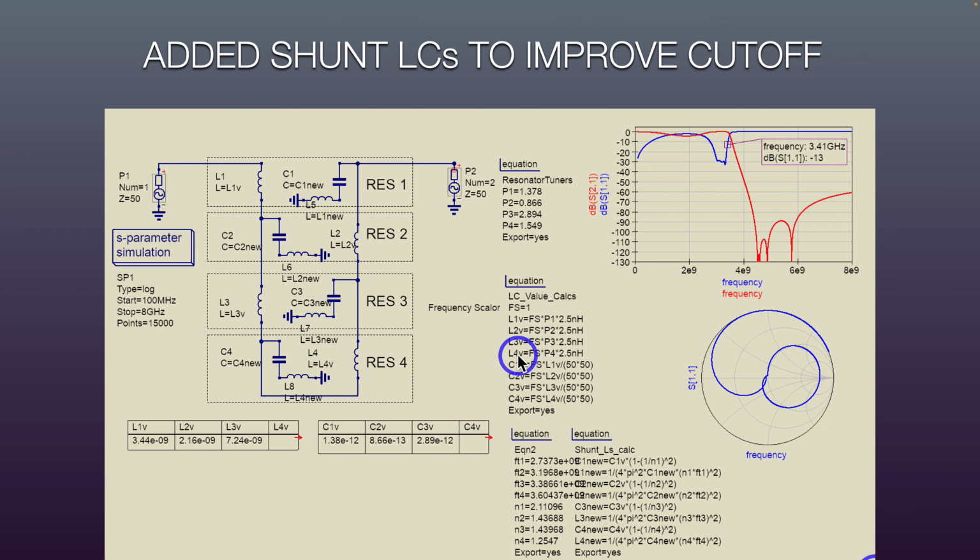Now you can also add a shunt inductor, an extra inductor on each one of the capacitors, and create these resonances out here that will then block higher frequency signals. So we've adjusted the L and the C to keep all of those in the 2500 to 1 ratio up here, except for the C we've added in an inductor. That then means you have to reduce the amount of capacitance to account for this inductor, so you make those a tunable parameter. And now I can just use adjustments of tuning variables to move all of both the in-band resonances and the out-of-band resonances around.